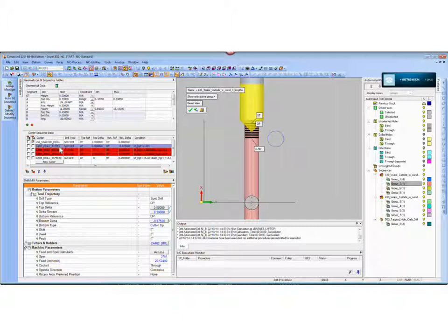And then each one of these has a range. So this tool, well, this one's also a 5 length ratio, and the reason is because it may be possible that I can finish the hole with that drill. So if that's the case, I want to go ahead and finish the hole. That's what this line says. And then this one, of course, is the 15 length ratio, and here's the 30 length ratio. So I set up these conditions. I define a range this tool would be appropriate for, and then it just processes. It looks at the ranges, matches it to the conditions, and it programs the holes automatically. And it really works nice.